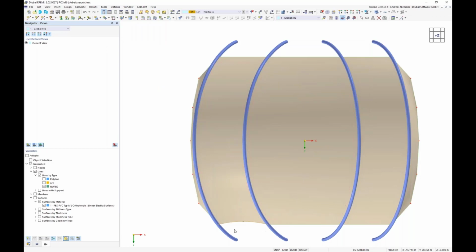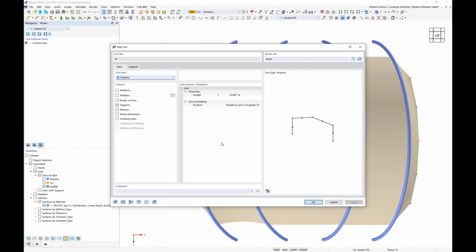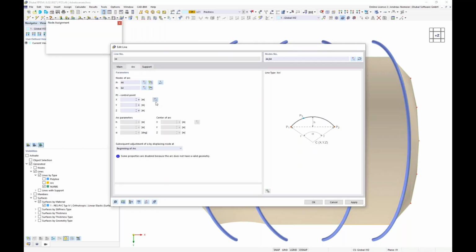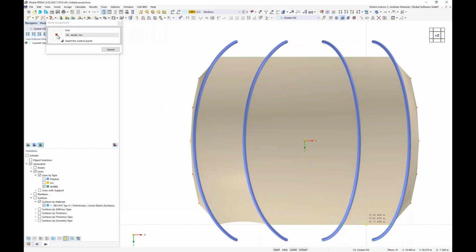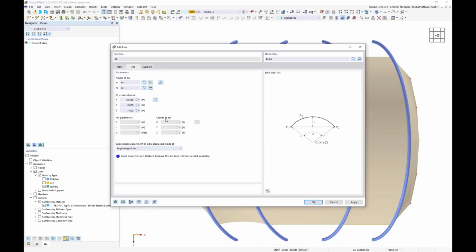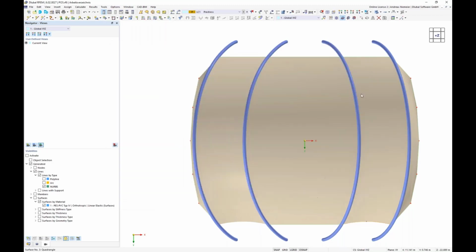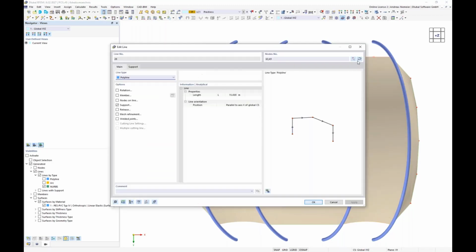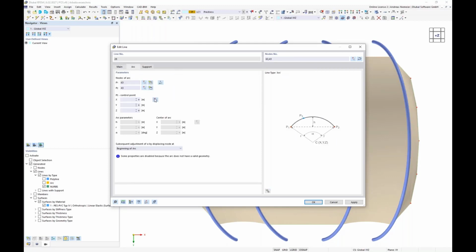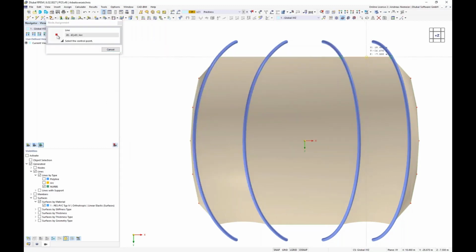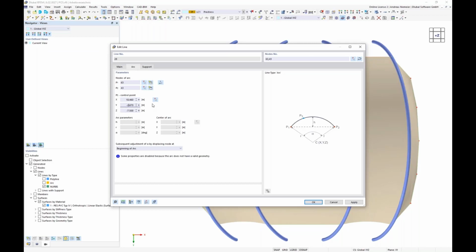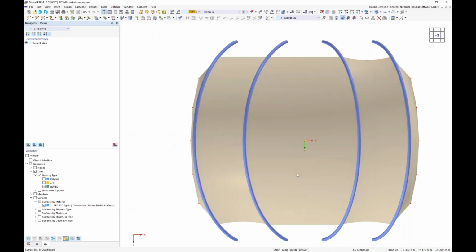It's only so that we can produce more mesh nodes in this situation, and we have to do this for all situations. So we use arc again here, as center, and change here to 5, and now also on these lines, type arc, control or sag node, and change this value to any other value.